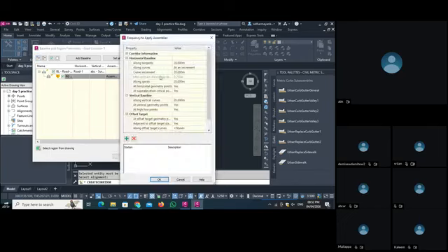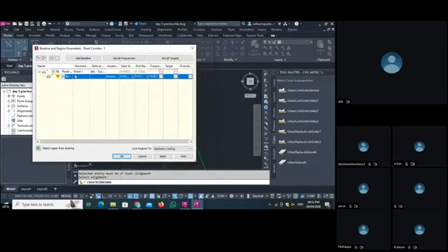Frequencies: you can set your frequency, like here in the horizontal baseline, the frequency is set as every 20 meter interval. If you want a more focused area, you can set it as a 10 meter interval. So at every place, for a curve increment, I use 10 meters. For a spiral also, I use 10 for the baseline. So I set all this as 10 meters, and then I select OK here, and now all is set.